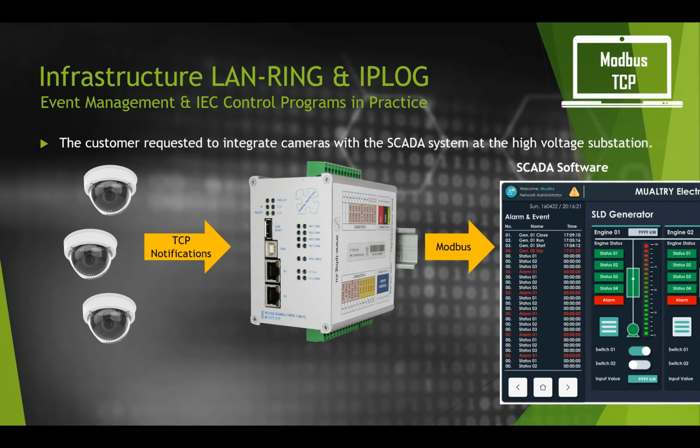iPLogs can also help with integration into SCADA software in power, industry, and similar applications. IP cameras transmit the required status information in the form of TCP events. These are the standard equipment of most modern IP cameras. These states are received by the PLC iPLog, written into the internal Modbus registers, and read from them by SCADA via Modbus TCP.